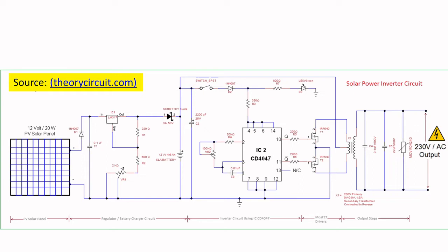It will be generating two continuous different states. That is a speciality in the astable multivibrator. Another thing you want to understand here is very important. Based on this only, the frequency will be generated here. The full oscillation will be taken from the 13th pin, and half of the duty cycle will be taken from the Q, and the other half of the duty cycle from the Q bar.